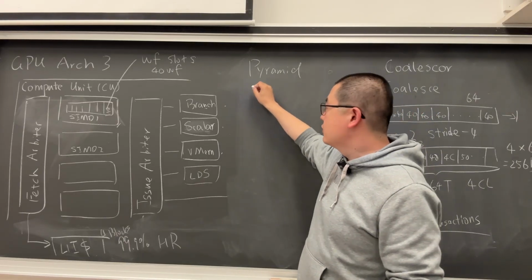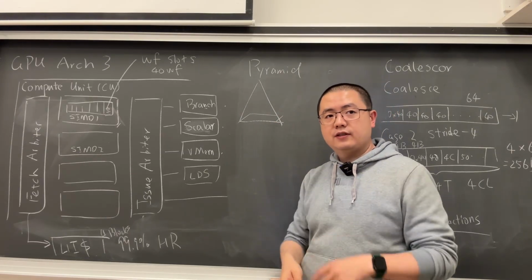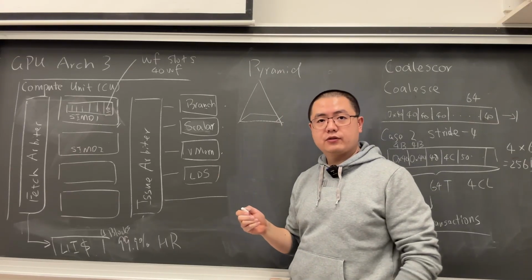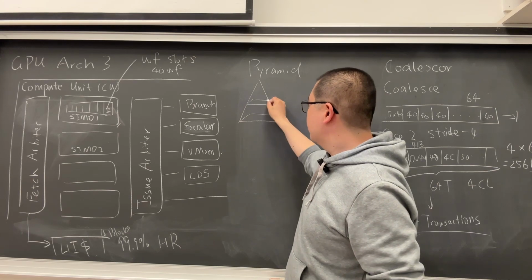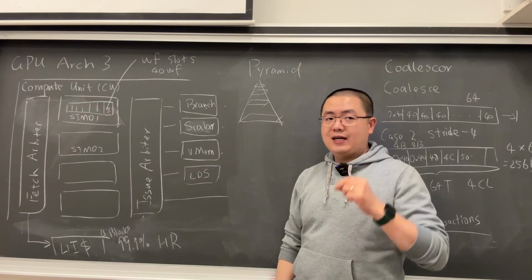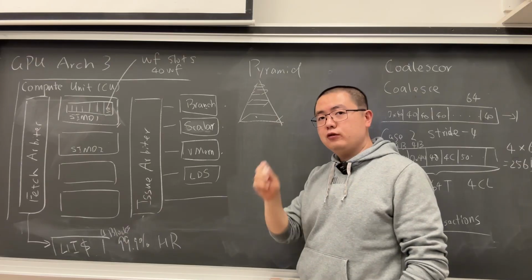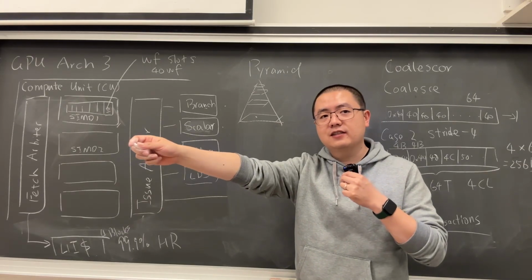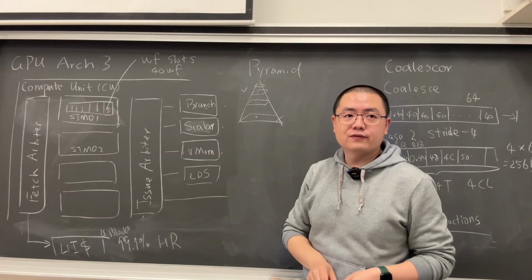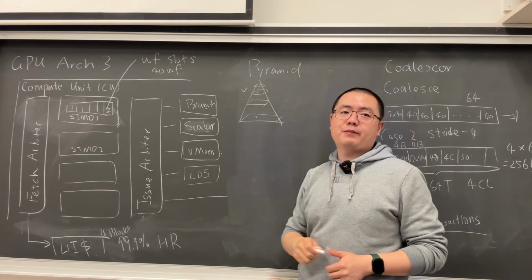It is this way. You have a texture image, right? If on the screen it is very far away, you don't really need the full resolution image. You can use lower resolution. So there's an image with half resolution, 1/4 of the resolution, 1/8 of the resolution, right? GPU allows you to specify, okay, I want this one at this location. Then the hardware will automatically determine how far away it is and which level we need to use, and recalculate the address to get the equivalent pixel. So think about how complex this operation is. These are all built into the pipeline.